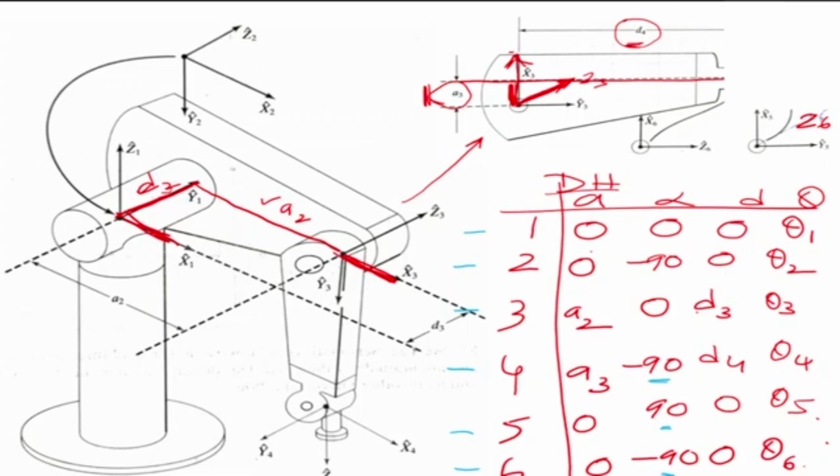Okay, and when we multiply them all out, we basically get the relationship between the last frame and the 0 frame. So it is advisable that you try this out by yourself, because you should be able to assign DH parameters correctly, then find the DH parameter table, and then from the table, take one row at a time, put it in that generalized matrix, and proceed. Okay. So today's class we discussed the generalized matrix, which will take you from one frame to another frame, and by using which the program actually does forward kinematics and inverse kinematics. So when you're writing a program, you have to use that matrix.